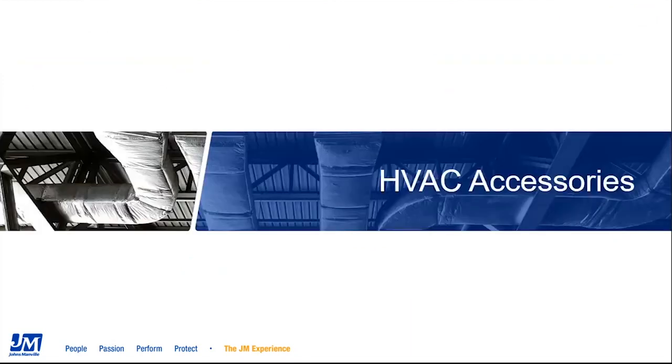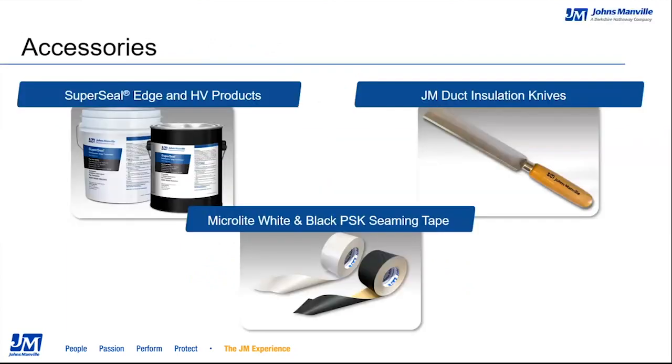So really quick, I'm going to touch on our HVAC accessories. We have just a few that we now offer. In the top left-hand corner, we have our Super Seal Edge treatment and HV products. The HV product stands for high viscosity. It's a trowelable, gap-filling type coating that goes into the duct system. Great for nicks or duct dings or gaps or scratches in the duct. And the edge treatment is for re-putting on the edge coating. So if you're cutting small pieces, you can reapply that. It's a black, liquid, paintable, sprayable coating that goes on the outside edges.